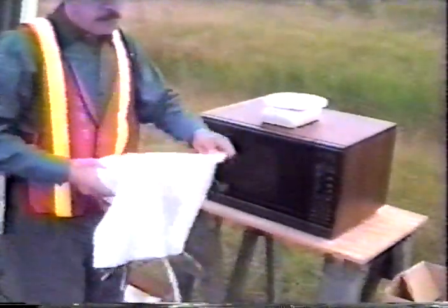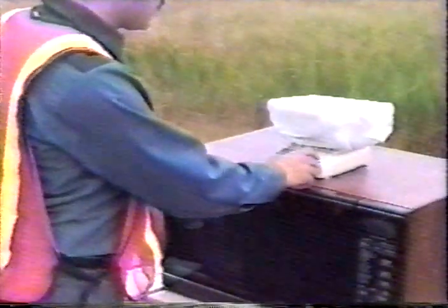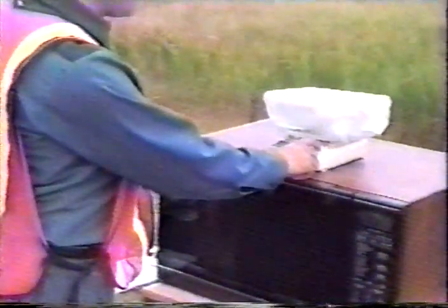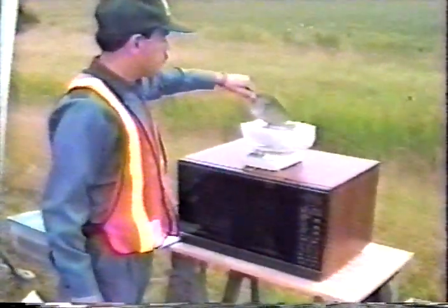With all the equipment ready, a sample of concrete is obtained and the test procedure is begun. First, the fiberglass cloth is placed on the tray. Both are weighed and the scale reading is written down. Call this initial weight WI. Leaving the tray and cloth on the scale, approximately 1,500 grams of concrete are added and are wrapped completely in the cloth.